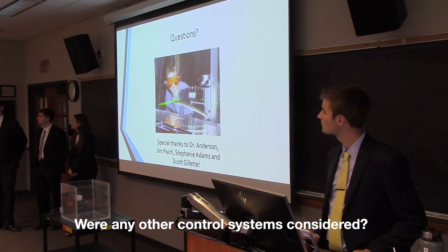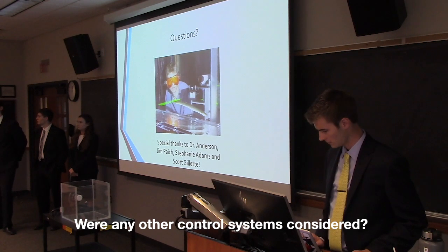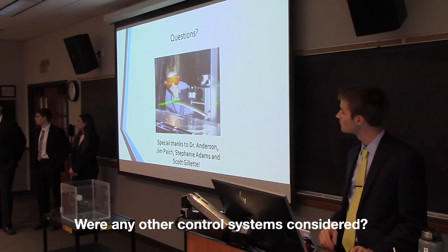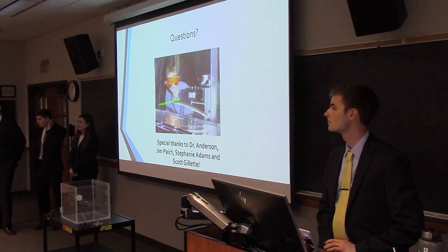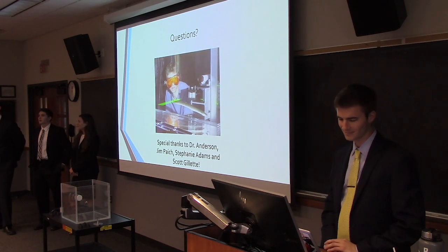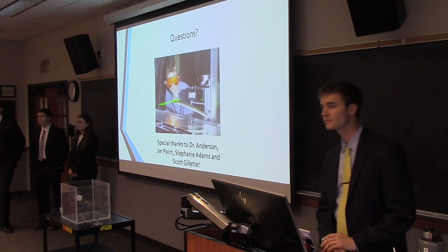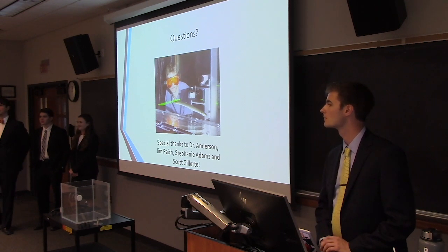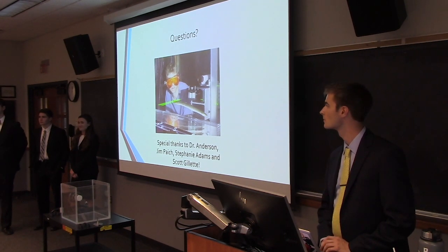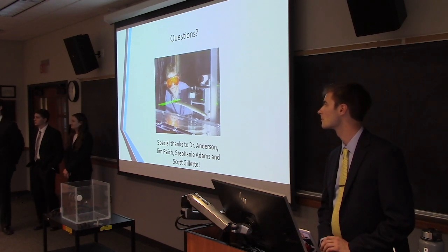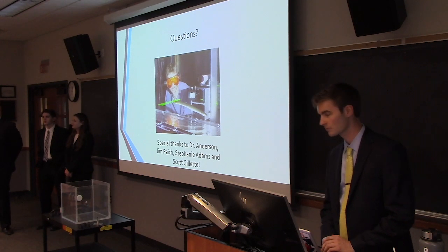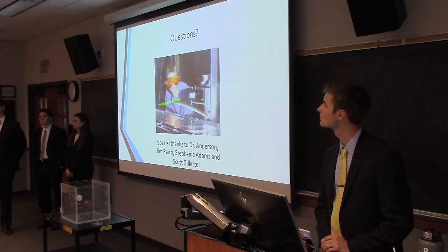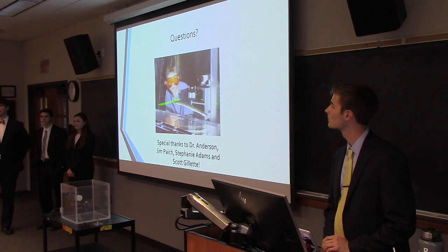No, the one that I looked at was just the proportional and integral control. The problem that I have with the system is that it's operating on about a 4-second update time. Because of that, I couldn't use derivative control because it wouldn't really impact anything. It makes no sense because the system is changing much faster than 4 seconds. That would actually relate to the question on things to be improved in the program: how do we make the update time more real time instead of 4 seconds. So we did not look into anything regarding other PID loops.